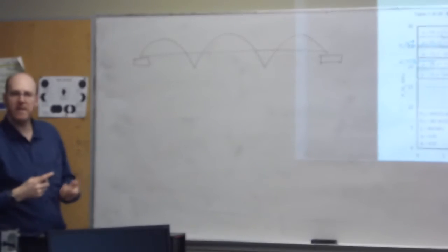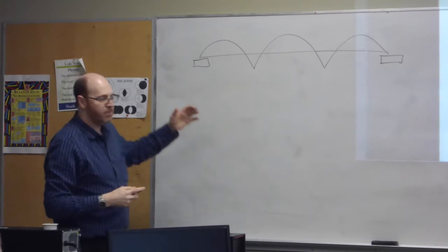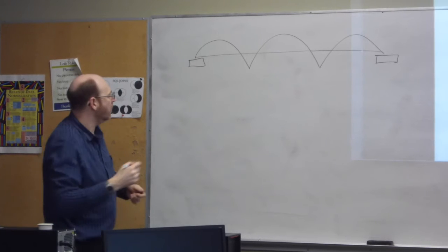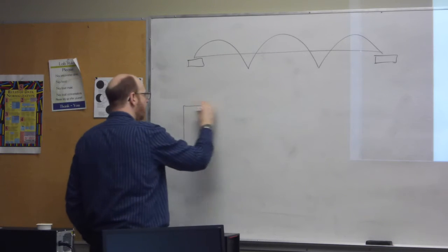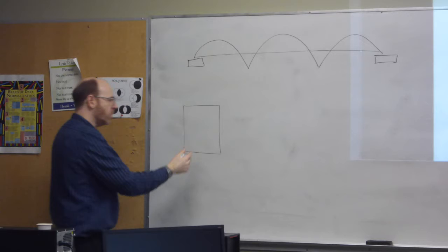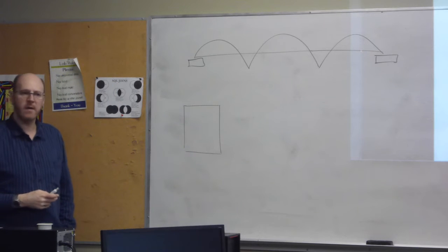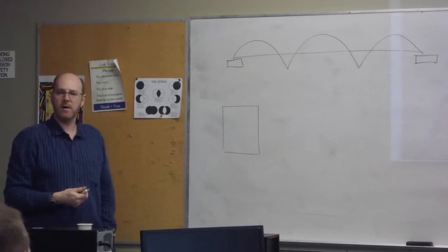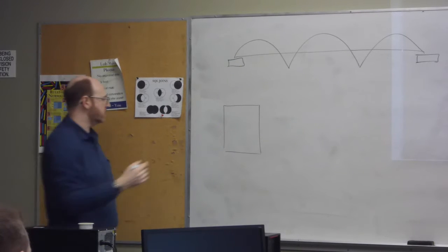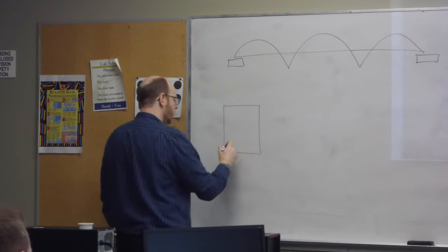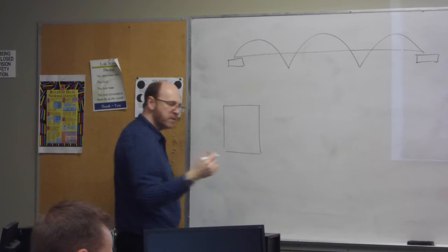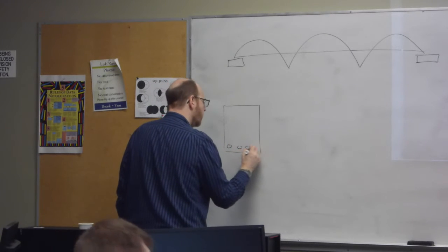Right, so when we went through and did our slab, we were focusing on bar spacing. Well, when we're looking at our beams, we've now got a finite space to put in here. And this is where we figure out our As required and how many bars. I put in equal multiples of full bars. So if I get like 3.2 bars, I'm going to round up to 4 bars on the bottom.